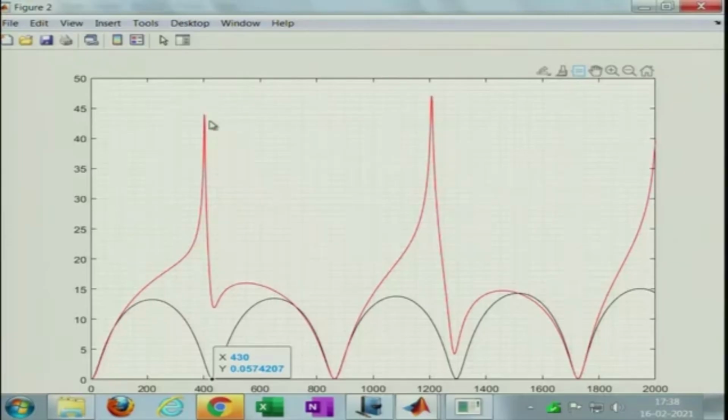Okay. Now, we have the peaks here. So, what do we do with this? We have this thing here. So, basically by L by 2 we cannot really just tune it, we have to tune the length, and anyways these are all based on plane wave models. So, this will obviously fail, there will be some higher order modes generated at the interface between the inlet pipe extensions and the annular cavity. There will be higher order modes generated due to the inductive effects of the evanescent modes. The effective length or the acoustic length of the pipes will increase. So, in order to tune that, we have to consider the geometrically smaller length.